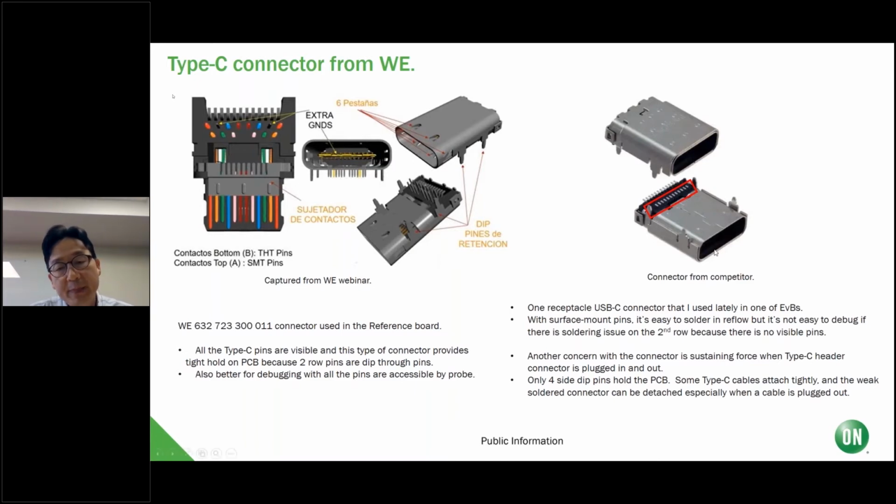I suspected the connector, and I found some issues with that. Also, this connector type has only 4 deep pins, so the holding power was not stronger than the Würth. So I personally prefer the Würth Type-C connectors.